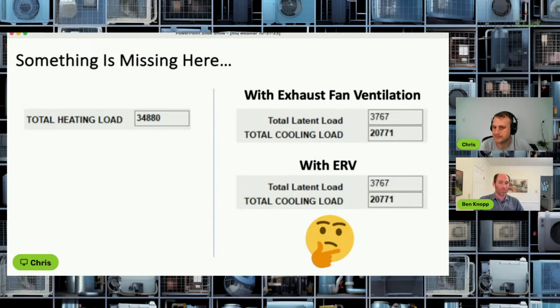I know when you start eliminating sensible heat load from your building and you don't do anything to lower the moisture, the latent heat load, then it becomes difficult for equipment to deliver the full effect that you need, which is to cool the temperature down and remove enough moisture that your relative humidity can be, ideally, somewhere in the ballpark of 50% in the summer.